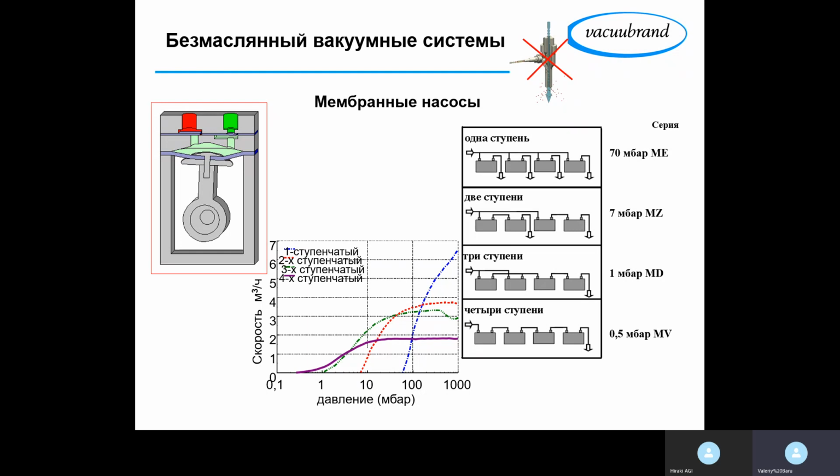If we're talking about the reactors, then just as I said, the separation won't be as demanding. But if we're talking about the Asahi products in general, then definitely there are higher vacuum applications, like short path evaporation, as well as the rectification column, because we are using rectification columns not only for low boiling substances, but also for high boiling ones, like in this case for the Azot customer.